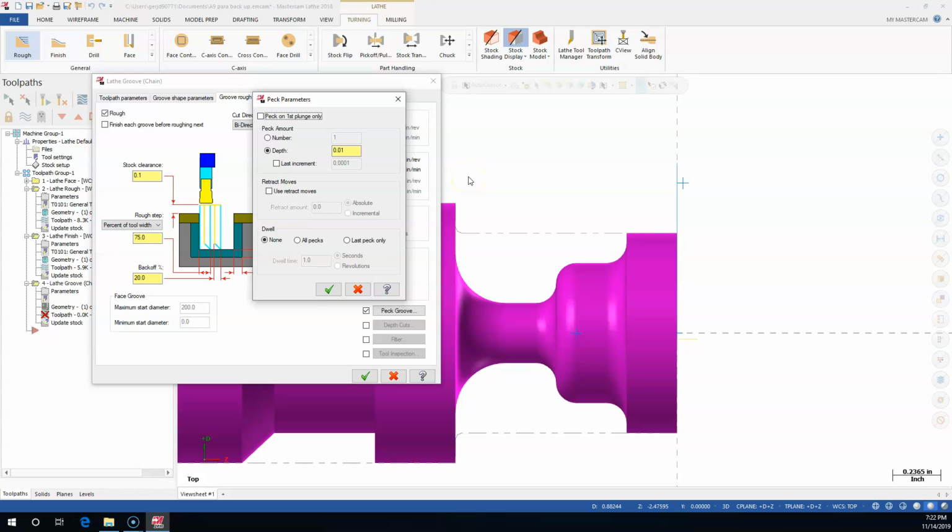And this is also moving us towards that kind of safety. If I get in and find out that the material is being removed real well and I think I can plunge for those next passes, then I'll bring it up or possibly increase the depth. So at that surface speed per minute, as this makes a revolution, 10 thousandths is still going to pull up a pretty good chip, and I want to give it a chance to eject out of those grooves as it's being made, rather than generating one long stringy chip.